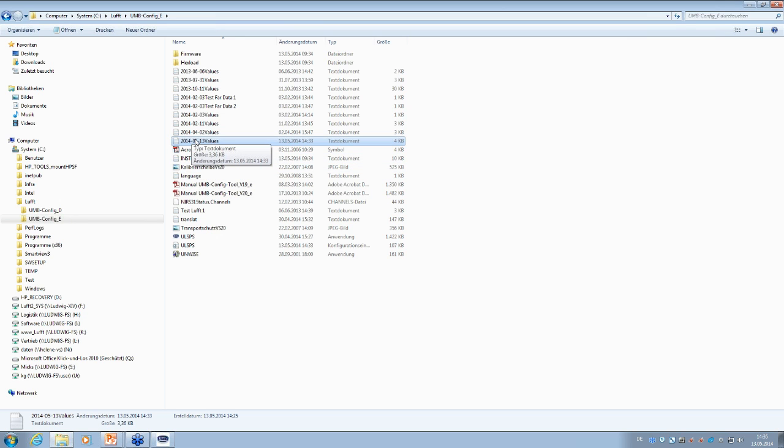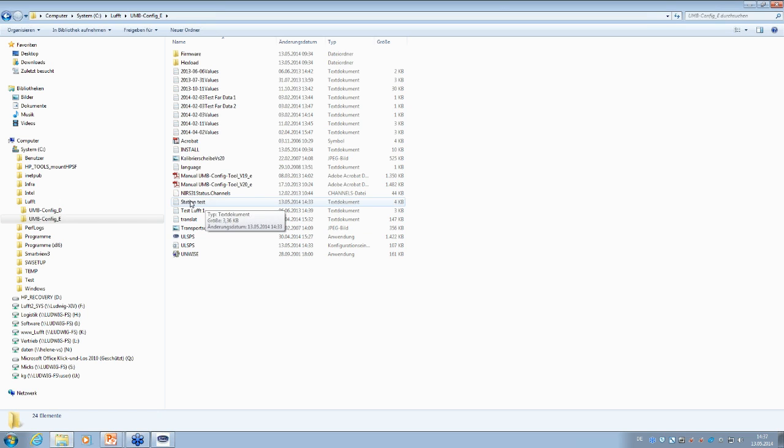So what I always recommend is to do the first measurement and check if the measurement values are okay. If everything is okay, go into the folder, open the text file, and check if the text file is okay. If it's okay, rename it. You can, for example, use the station name, station test, for example here, not teat, test. Then you store it, it's stored here, and then you can drive to the next station. Do the same thing again, automatically you start a new measurement. Again, the text file with the syntax timestamp and values will be generated. Then do the same: you start a measurement, everything will be stored in the timestamp values.txt, rename it with the station name of this station, and so on.